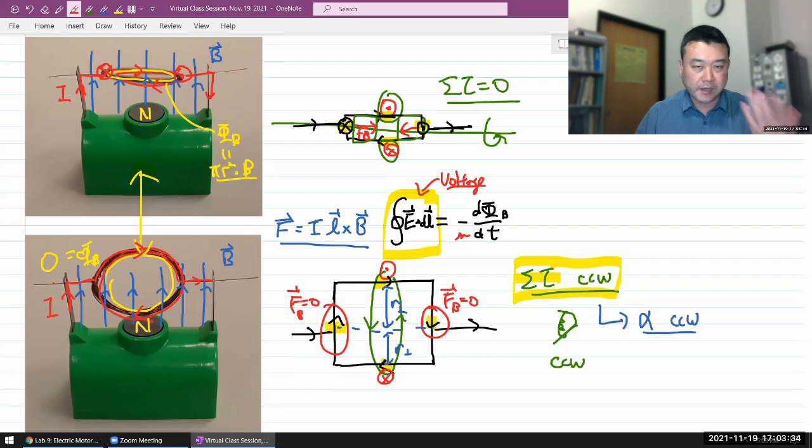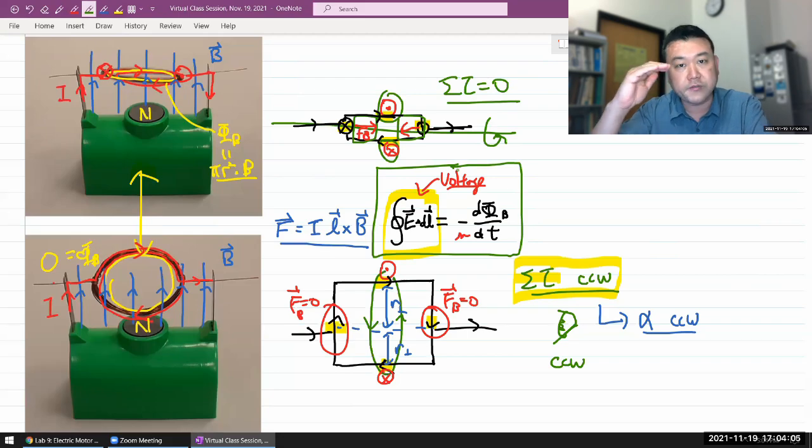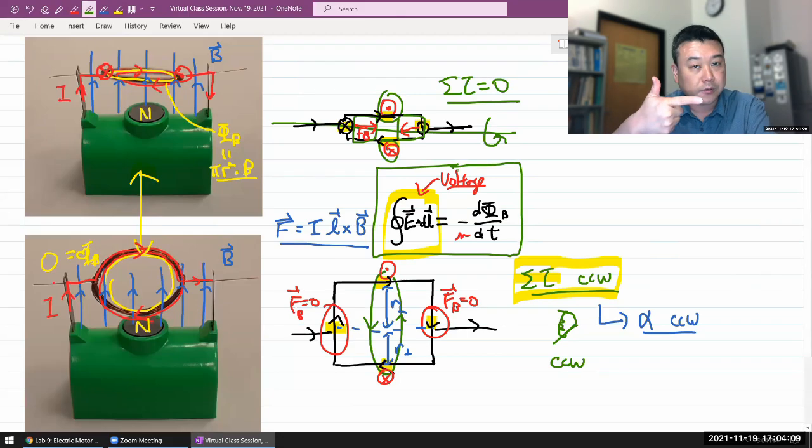Or in the case of a more realistic motor, the only power that needs to be drawn is the same power that's needed for the motor to do mechanical work, either against the friction or against the load that you are imposing. This part of the operation of a motor is important because it makes a free-running motor safe. It has some natural maximum speed that depends on the magnetic field and applied voltage. So the applied voltage acts as a natural regulator. It limits how fast the motor can spin. And if you want the motor to spin faster, apply a higher voltage, and then it'll be able to spin faster.